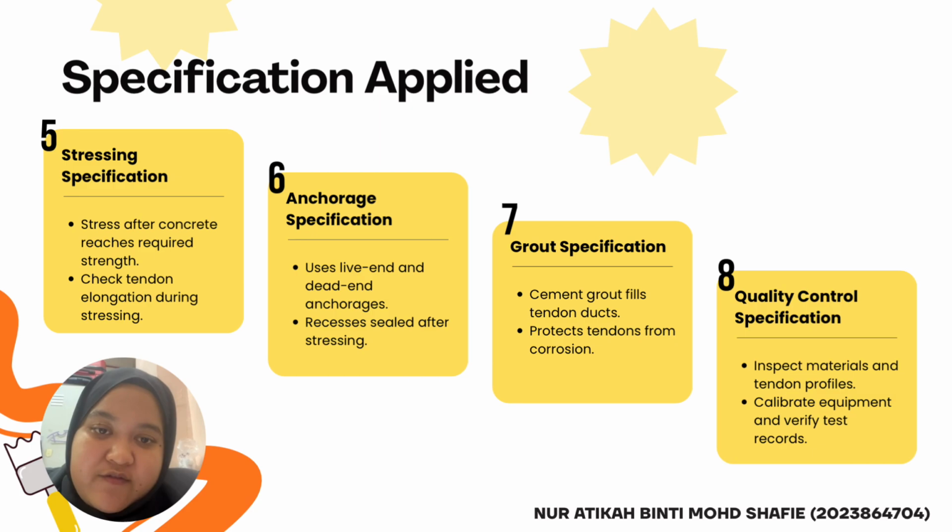For number seven, grout specification. Cement grout fills tendon ducts and protects tendons from corrosion. And the last one is quality control specification. Inspect materials and tendon profiles, calibrate equipment, and verify test records. That's all from me. Thank you.